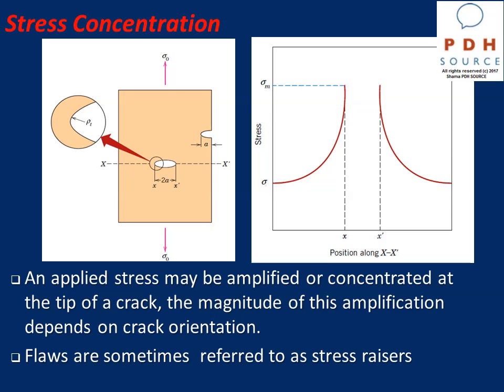Let me define what stress concentration is. Basically, if you have a plate such as this one, and this plate has some kind of cracks, we may notice amplification of the applied stress in the vicinity of the crack tip.